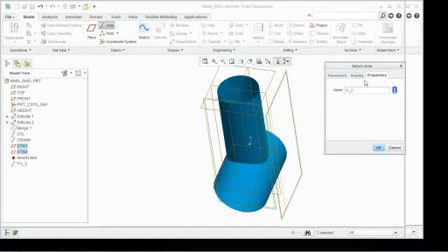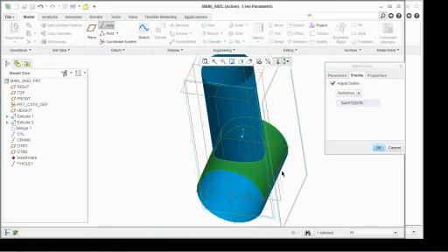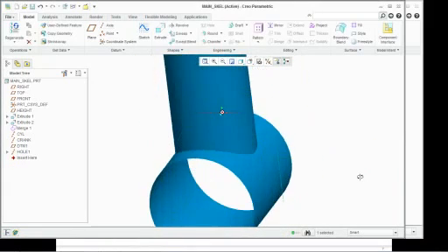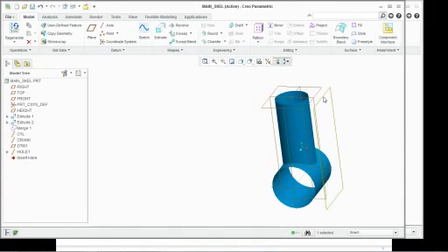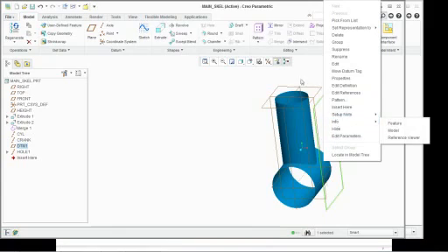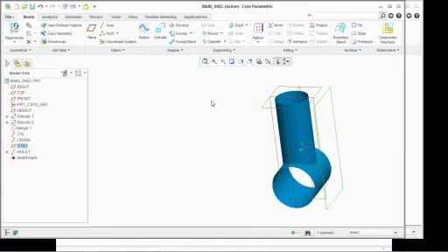And I'm going to actually take this axis and change the name of it to hole 1, and then take the display and adjust the outline down to a reference of this top face here. Notice that the axis did get shorter. Click OK. Well, maybe I want to take this one here and change that as well, but that's not necessary in this demo.